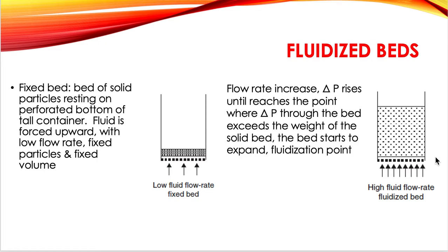A porous bed is constituted of a set of solid particles that are placed randomly, and to characterize this bed, a few parameters are considered. The first one is specific surface, or specific surface area, and this specific surface area can be for the entire bed or for a particle. The second parameter is porosity.